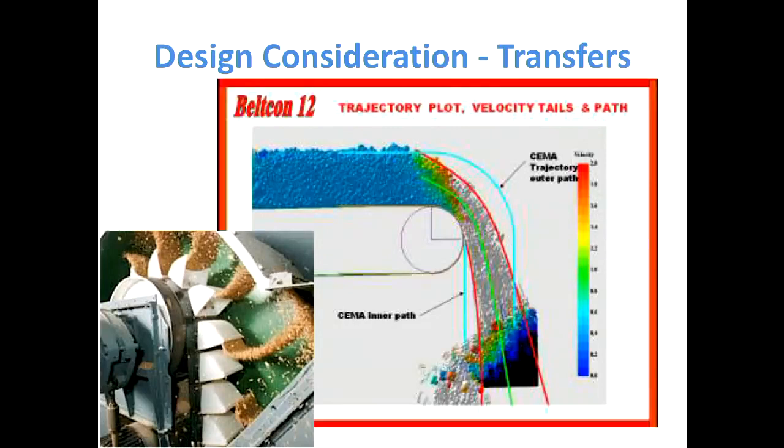Okay, trajectory. This is good for you to see, because most people do not understand what happens in a bucket elevator. So this is a trajectory. There's discrete element analysis and all this kind of stuff here. They come up, look, they're not even getting very close. They like to think they are, but what they do is eliminate all the particles that are below 20 millimetres in size, because the computers just can't keep up. But it's your fines, as I've told you, that cause you the problem. For the trajectory, there's about 6 different ways you can calculate it, and they're all different. But sometimes when you're looking at your linings and things on chutes, you need to look at it.